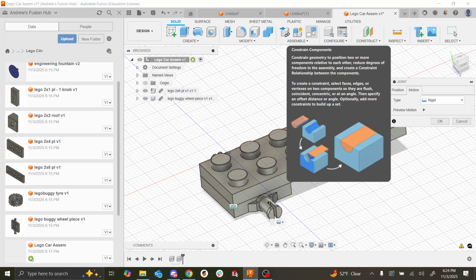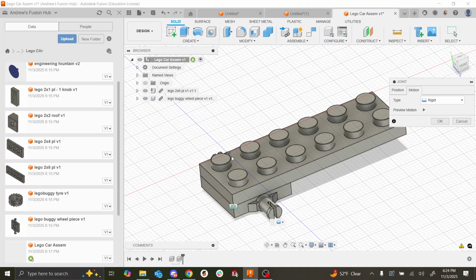So that's why even though it's new, I think it's a really good one, and I'll teach it in a second. But yeah, that's how you do the joint tool. One thing I did discover recently, through my testing, is there's a bunch of more advanced features, like using intermeshing gears, or when you're setting gears to intermesh with each other, you need to use the joint tool to create those relations.